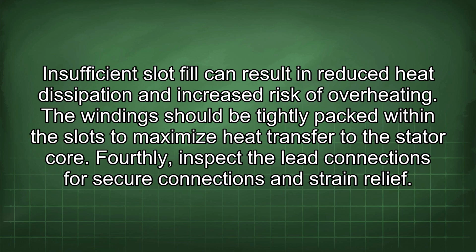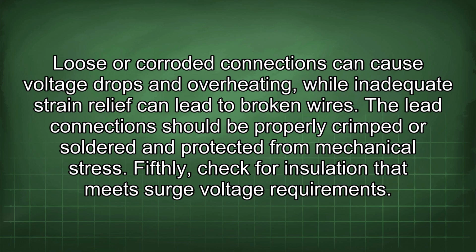Fourthly, inspect the lead connections for secure connections and strain relief. Loose or corroded connections can cause voltage drops and overheating, while inadequate strain relief can lead to broken wires. The lead connection should be properly crimped or soldered and protected from mechanical stress.